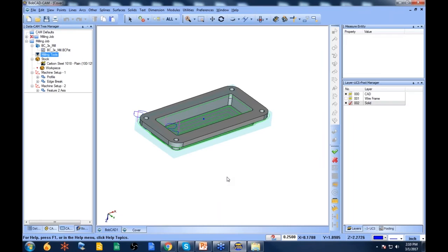So in order to control the order in which things are posted in, we're going to use the machining order dialog. We can set it feature dominant, we can set it tool dominant or tool dominant across setups. Now, the CAM tree, John asked a question, why doesn't the CAM tree reflect the order changes? Well, because we're a feature-based CAM tree, so you have a feature, it's associated to geometry, and it contains operations, okay?